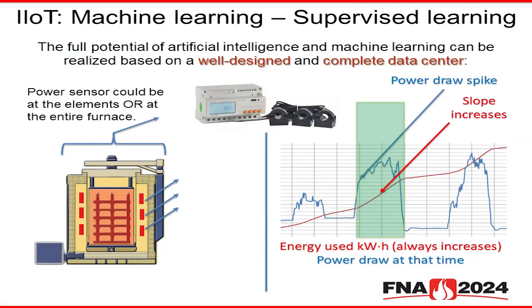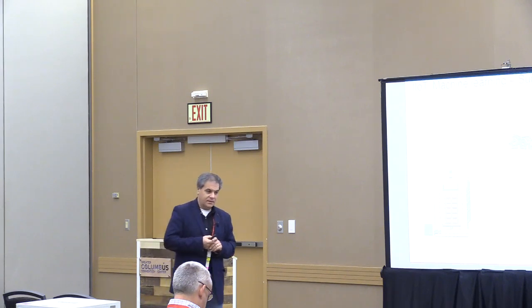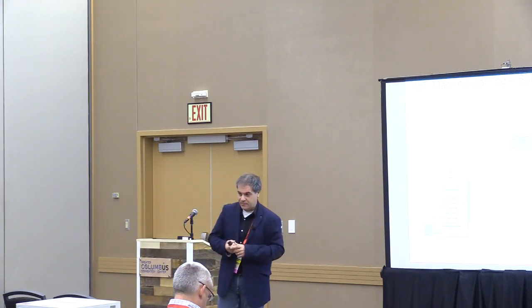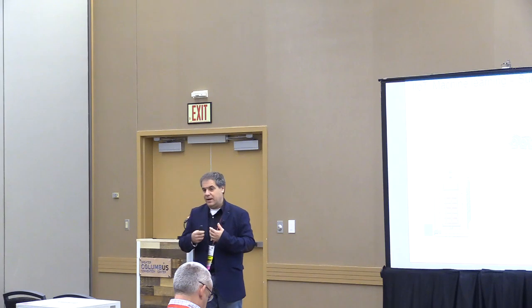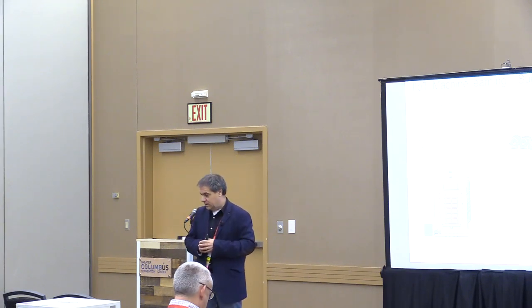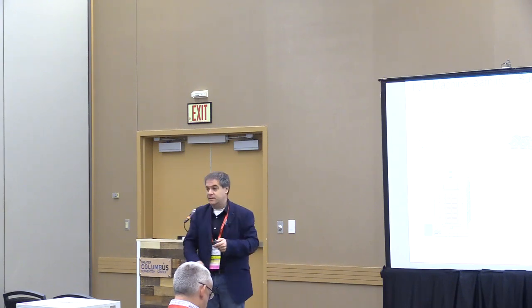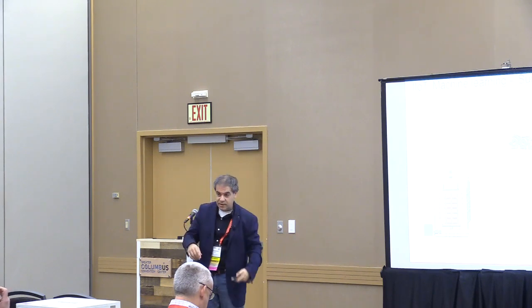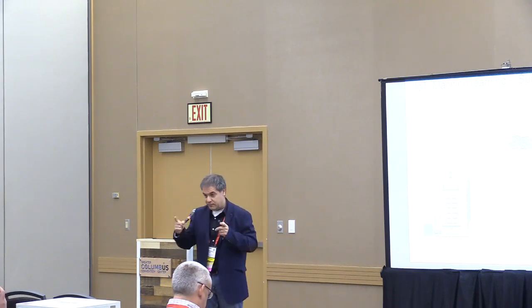Now, one of the things about sensors: some furnaces have sensors on temperature and power, it's guaranteed every furnace would have. Other sensors I may not have. I'll give you an example of how I could derive a sensor from other sensors. So in a vacuum furnace, I have 12 thermocouples. That's 12 TCs. In Excel, I have 12 lines: temperature, time, going on forever. There's always new data, 12 of them.